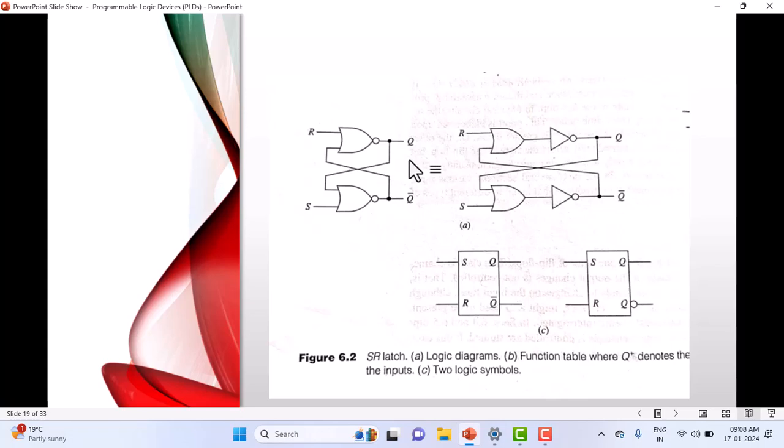Let's now analyze what will happen if I make both as 1, 1. Let's remove all these things, just look at this, how I analyze. Now look at this. I started initially with 1 and 0. I made both as 1 and 1. Now let us start with this. 1 comes here, 1 and 1. The next state is 0. I would like to write here an arrow mark, next state is 0. The 0 comes over here, 1 and 0. This is what, 1 and 0 is 0. The 0 comes here, 0 and 1. It is 0 only.